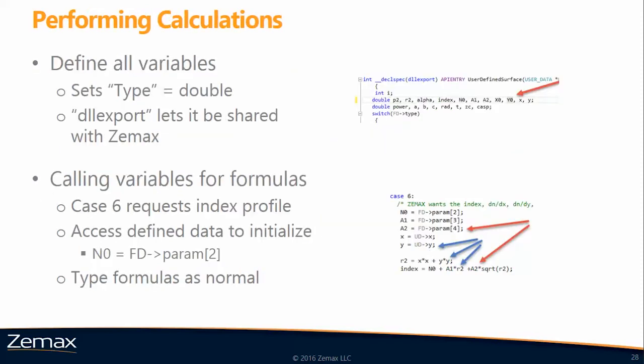Any variable used throughout the code must be initialized in the DLL export command at the beginning of the source code. After this initialization, a variable can be assigned a value through simple equivalency statements. This value can be a value from OpticStudio or the output of a calculation which will be in turn passed to OpticStudio.